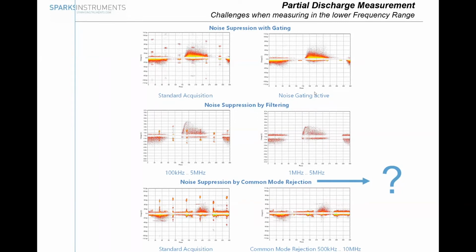The systems also have a so-called gating. The gating is the system have an additional channel to acquire the noise. So whenever we can measure the noise with this separate noise gate cancelling channel, this noise can be measured and then it is removed. With a big advantage, we do not lose any magnitude information. Of course, we need to find the right spot to measure the noise. This is then another challenge.